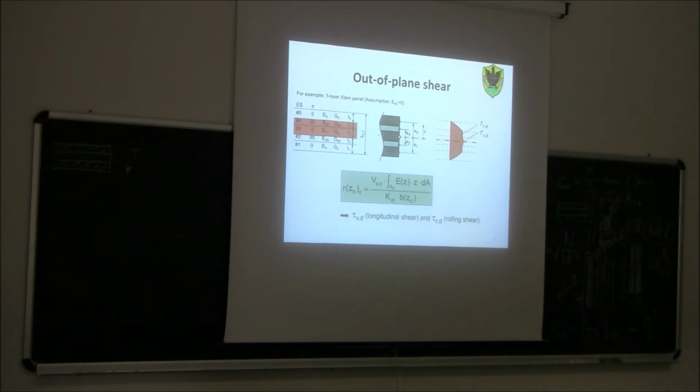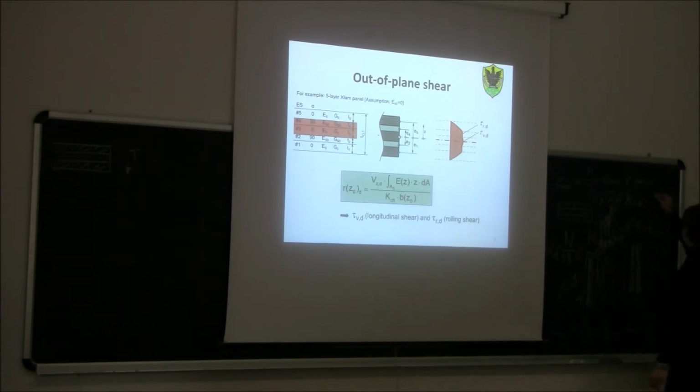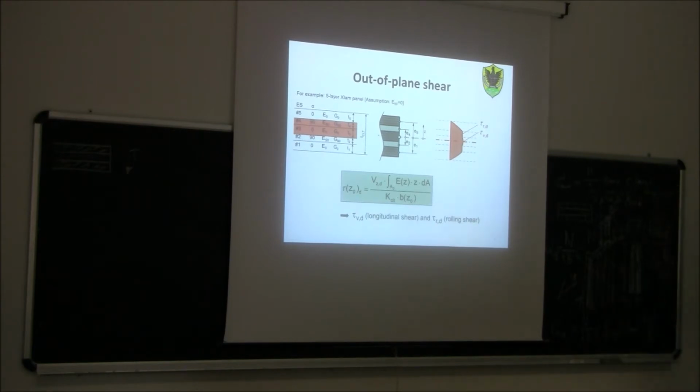The practical case could be, for example, if you have a beam on two supports, and you load the beam on the overhang, something like this. In this case, in this inner part, you have only bending moment and no shear. But anyway, if we have shear, for sure there is a bending moment, because you cannot have shear without bending moment.